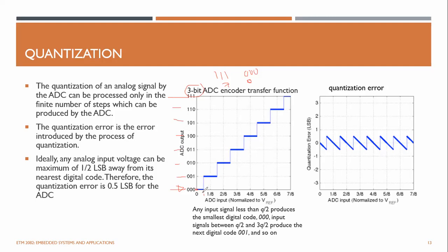So if the original reference voltage is 0, you can have 0, and you can go up to half of that step, right? In this region, it can only put your digital value here. If it is over half of that value, 1/16, any voltage level over that you will just push to the next value, because digital values do not have half values.